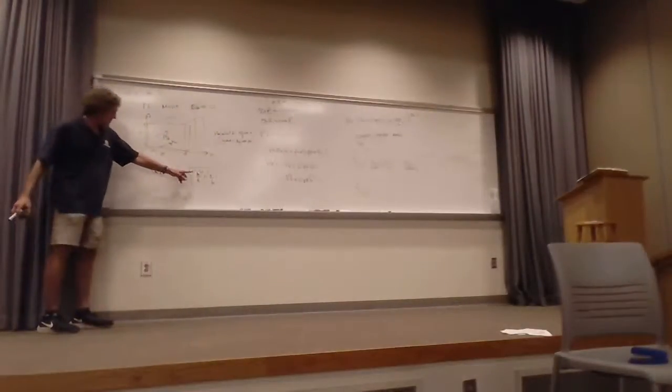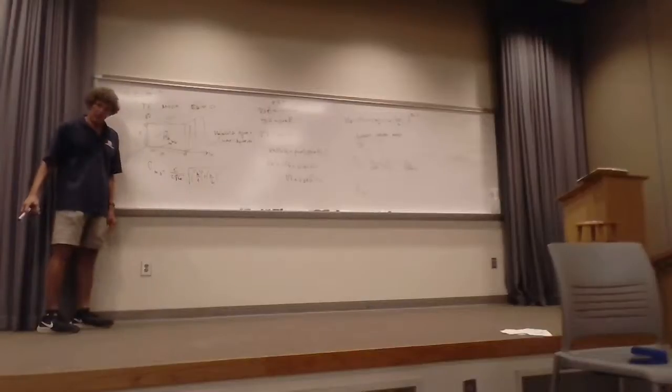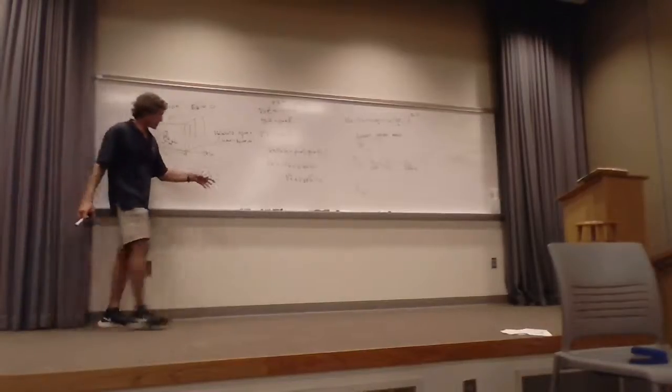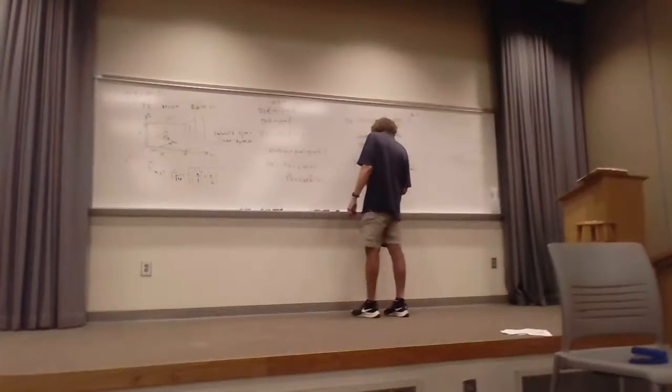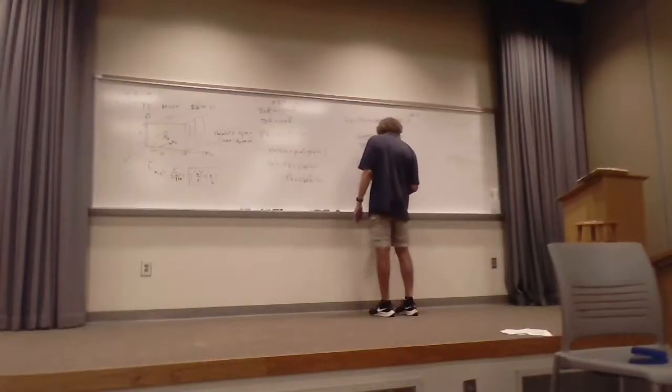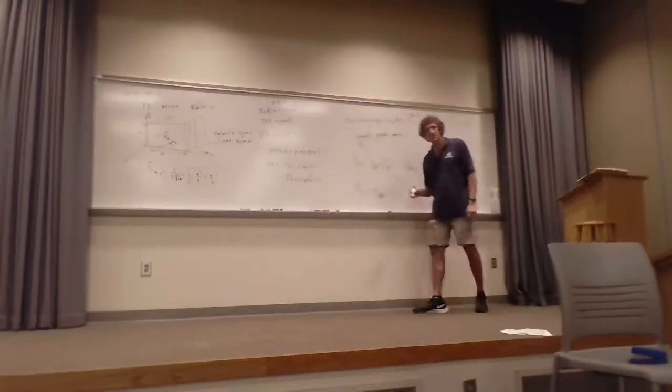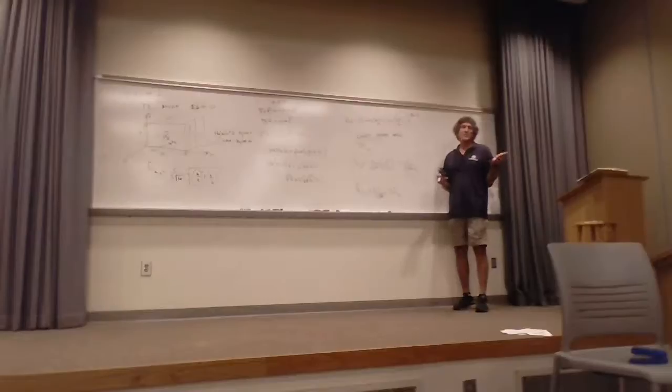So if it's a 2-0 mode, it would be 2 over a squared, right? And this would be 0. So this would really be 2 times c over 2 square root of epsilon relative, or it's really 2 times the first mode, the 1-0 mode. You all see that, class? So if you have a 1-0 frequency of 1 gigahertz, the 2-0 will be 2 gigahertz. You all follow me on that? It's that simple.